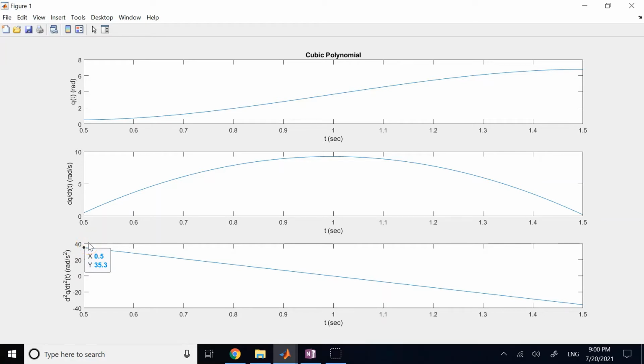Maybe, okay? So we can look at one simple motor here with some specs, right? See what is the Tmax, what is I for it, and what is theta dot. And as I said, this omega and this guy times I, which is torque, are not independent from each other.